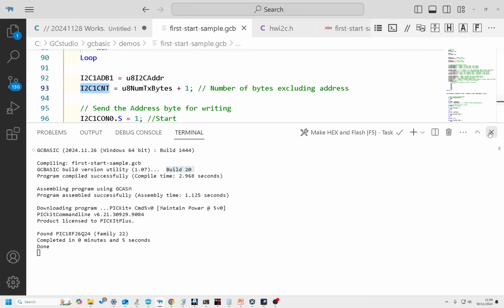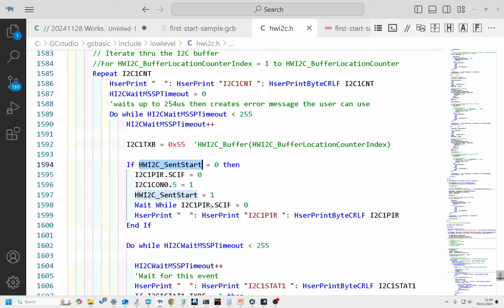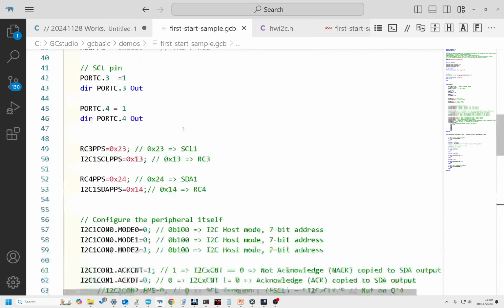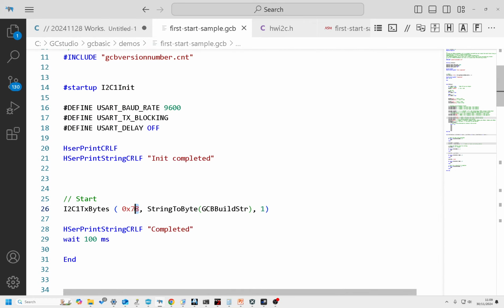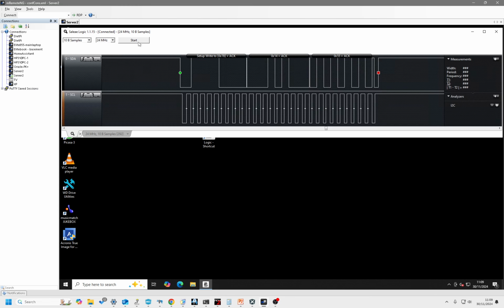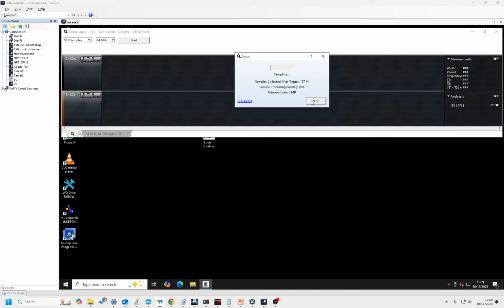So my job now is to take this code here and convert that over into the library. And the library will, as I said, have things like error checking, so that we can actually detect when it didn't find the address. And what would didn't find the address be like? Well, if I come into my source code and change the address at the top of the program, I'll change that to 76, compile it. I'm trying to get there fast enough. Start. Hopefully I've captured it. Let me have a look. Found it. Yeah, I should have captured that.